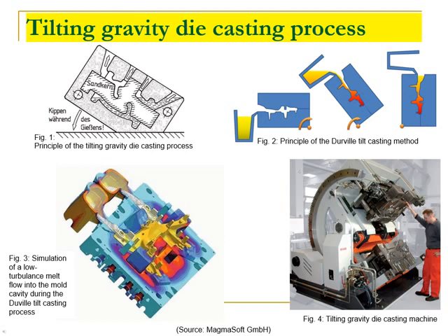This causes the melt to flow into the mold cavity with a low head and at moderate flow rate, as illustrated in Figure 3. This process is used for casting materials with a high propensity to oxidation and foaming, such as aluminum gravity die casting, and aluminum-bearing copper alloys, in particular brass gravity die casting. The tilting towards the pouring side results in a low feed rate in the gate, helping to reduce oxide and foam formation, and the liquid metal can flow into the mold cavity smoothly and with low turbulence.